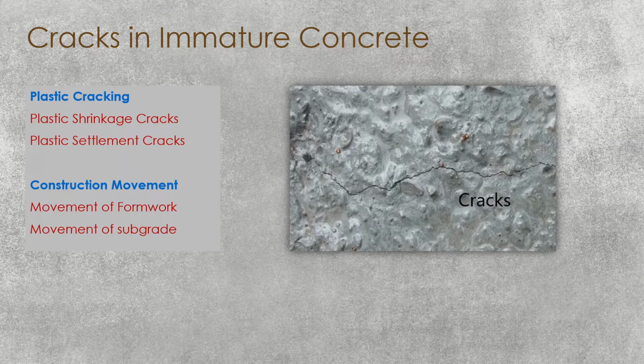Plastic settlement cracks: moisture movement could also be one reason, and the reduction of volume of the concrete as it hardens may also be one of the reasons.